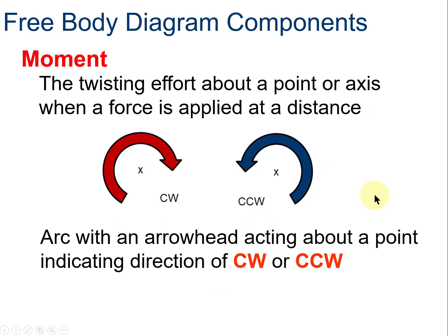Okay, a moment is a twisting effort about a point or an axis when a force is applied at a distance. It's called torque in physics. And it's shown as an arc with an arrowhead acting about a point, indicating direction of clockwise or counterclockwise. So basically a moment causes something to rotate. Again, moment is the same thing as torque. And a force causes an object to move in a linear direction.